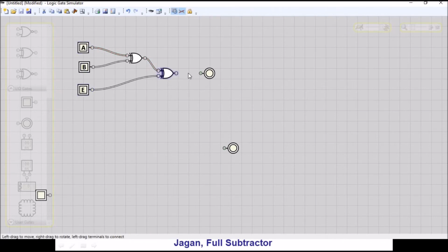Okay, so what is this? This is nothing but your difference D, right? So what is the expression here? What do you get? A XOR B XOR with E, right? So E here will just take it as B in. Okay, so we are done with the difference.